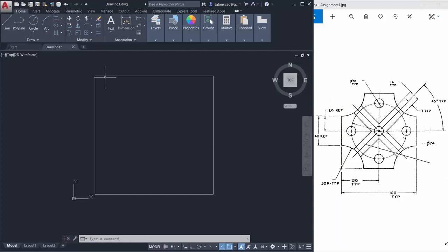this drawing. So I'll go to circle command and I'll choose center radius method, and I'll pick this point as a center point of the circle. Now when I'm asked to give the radius, I'll type 30. Next I'll create the circle.